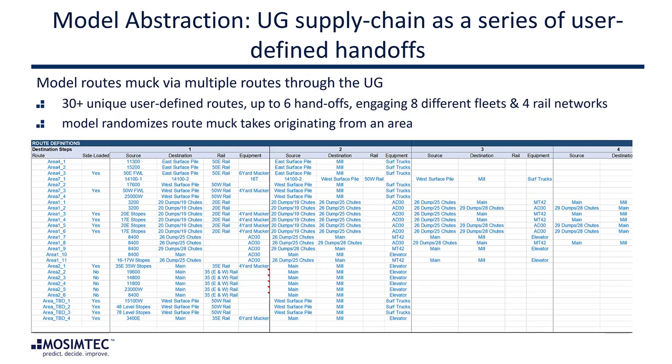What we did in this model was instead allow the users to define all potential pathways from an underground area to the surface, all the possible intermediate storage locations or passes, and the equipment fleets that could be used for these handoffs. This way, the model randomizes the flow of ore through the network of route segments or handoffs, engaging different pieces of equipment along the way.